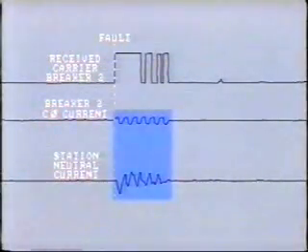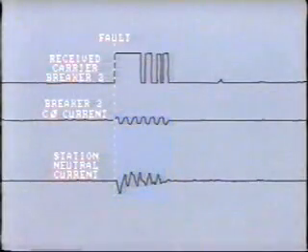Well, when the relays at breakers 2 and 3 compare the ground residual current with the distorted reference current, the phase relationship is unclear. The relays now mistakenly decide that the fault is in the trip direction and simultaneously suppress the carrier blocking signal.